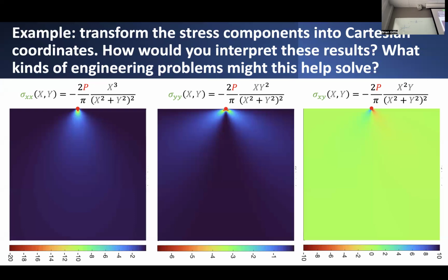And usually you can get around that by making some approximations about how you're actually distributing the stress. It's never actually going to be exactly concentrated like this. If you're dealing with, let's say, tires on a roadway, we're talking about not necessarily a tire applying a point load at this singular location, but most of the time tires are pretty flexible. They have some compliance. So when they compress on the surface of the roadway, they're actually going to deform quite a bit and spread out that load over a deformed area of contact.